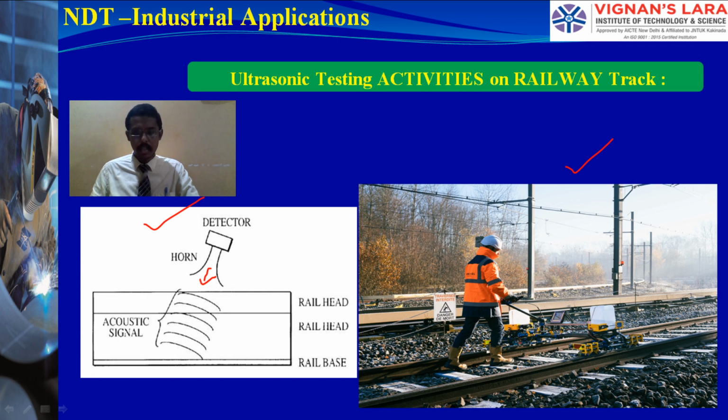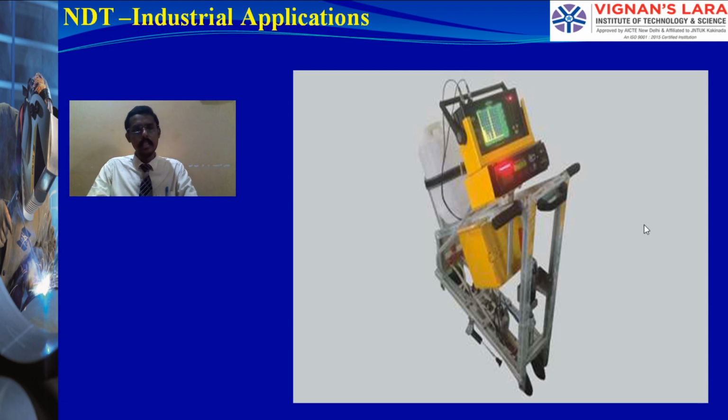You see, if you are keenly watching, here we have a camera and a stick with hands, and he is moving on the two tracks, one side track and the other. With this movement, he is able to pass the ultrasonic waves inside the specimen like this, like this, like this. He can send them, and he is able to do the inspections. So this is one of the setups of an ultrasonic machine.